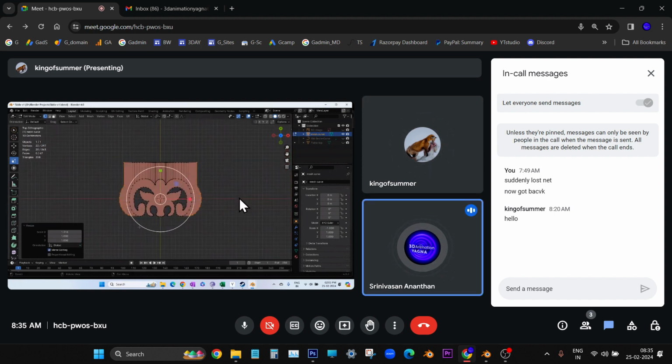Yes. Now you have to make it flat, right? So for that, go to the transform pivot point menu in the middle after global. Individual origins. Now, same x-axis handle, press hold, do the special manipulation, type 0. Now switch back to median point. It is in the same transform pivot point menu, below the individual one.